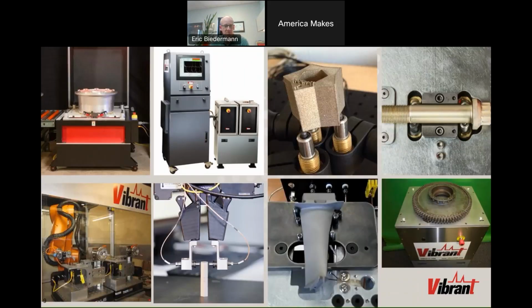PCRT systems come in all shapes and sizes, just like your components. And we configure transducers to hold and excite components in a variety of different ways. And that's usually an optimization between maximizing data quality and maximizing operability and throughput. So we can excite just about any part geometry. I mentioned that America Makes study that covered PCRT capabilities for AM part complexity.